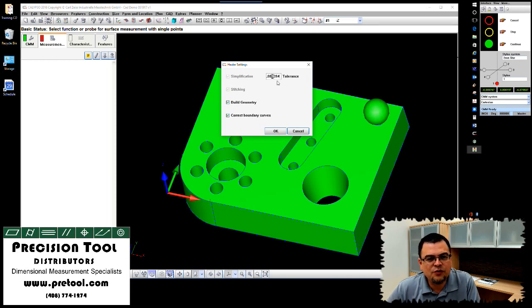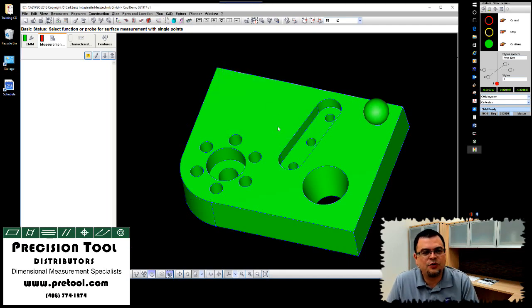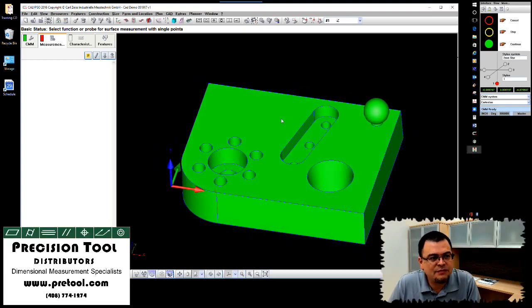How much do you increase it? Boy, that's a kind of a shot in the dark. I usually start by doubling the number and just go from there. I've really only had to adjust that number maybe on 2 models ever, maybe. So with that said, we can click OK. Now you can't overheal a CAD model anymore, so there's no danger in actually doing that process 2 times.